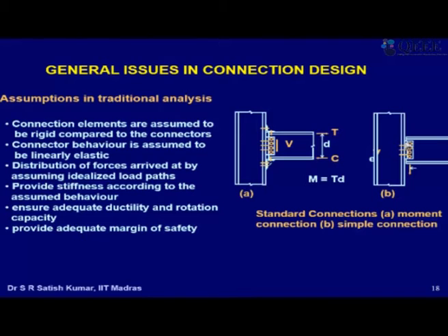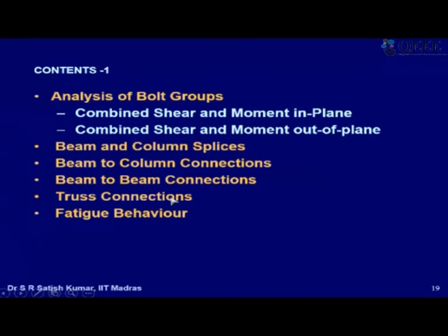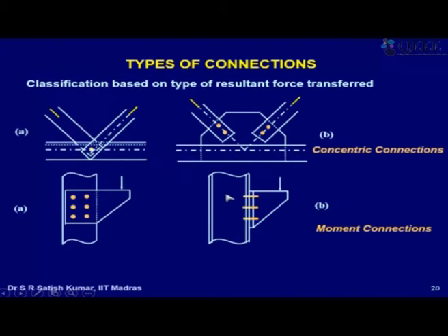If this angle is not going to bend or anything, it is going to be like a plane section in a beam and it remains plane, so my stress distribution will be linear, right? So our strain distribution is linear, so that is an assumption which enables me to calculate the force in the bolts. Okay, so those are written here. Let's go and see how we actually do it for real connections.